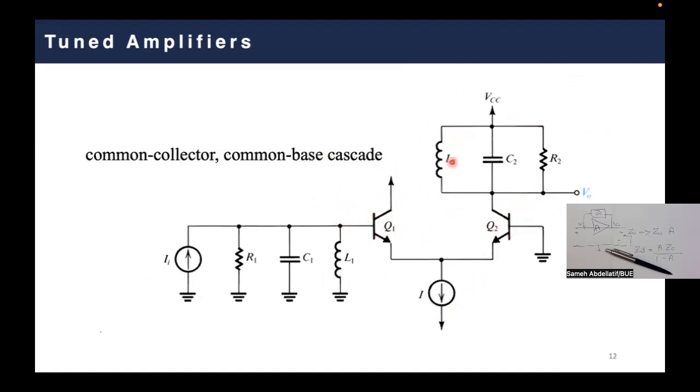And then you have this RLC filter. Again, the Miller capacitors here are totally disconnected, where still we don't have this input-output feedback capacitor. So these are some circuit tricks that we can use in order to reduce the impact of the Miller capacitance in your tuned amplifier and generally in your circuits.